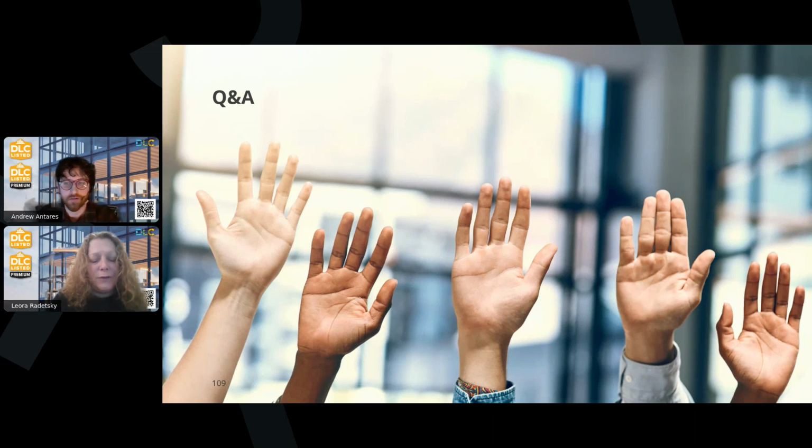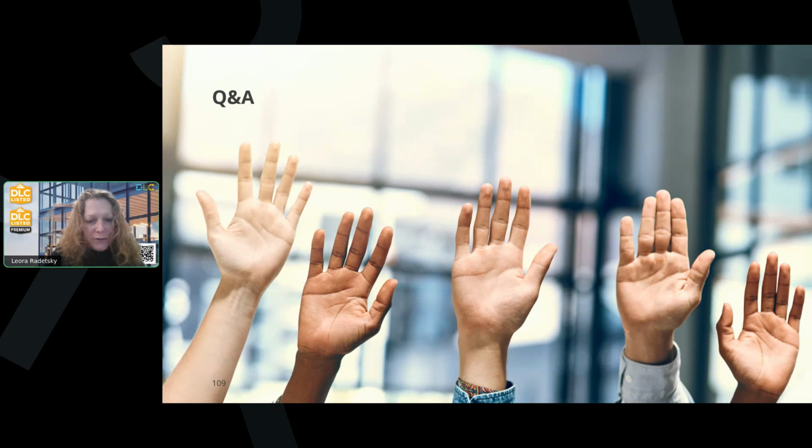Yes, that is a great question. So we have changed the requirements. They are now for the full fixture, not just 0 to 90. And the thresholds for the uplight portion of the distribution have also changed in the final requirements based on our research and input we received in the draft process. So you can use a tool like Photometric Toolbox, which is the one we mentioned in our technical requirements, or another tool if you'd like, and then meet those distribution requirements that we have in the TR. Great question.